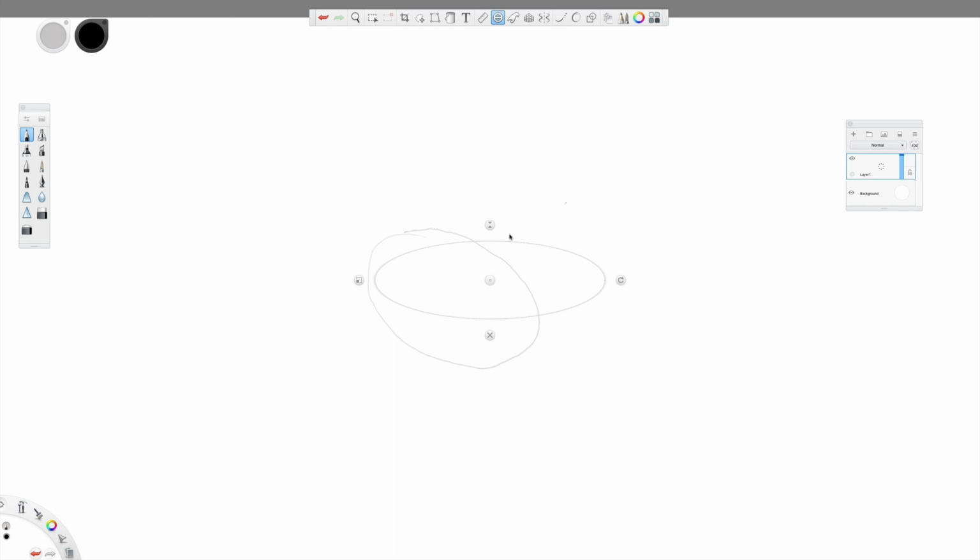And you have various other curves that you can make, very detailed, very precise lines and curved lines. You can see how we can make this ellipse. You can rotate this around. You can resize this and then X out. We also have this curved tool where you can do some very intricate, detailed, and precise curved lines.